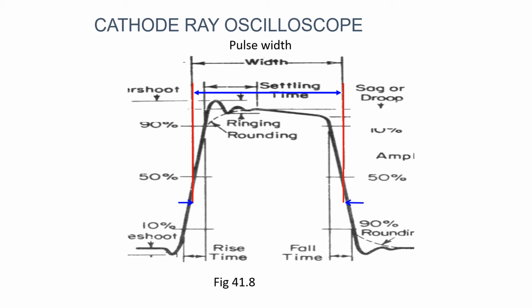So here the procedure, as I already told you, for measuring pulse parameters is, when we are measuring pulses, it is generally desirable to use the pulse source as an external trigger. The essential parameters of a pulse are the amplitude, the rise time, the fall time, the pulse width, duty cycle, delay time, and the pulse repetition rate. So the input waveform has steep leading and lagging edges, while the output waveform has measurable rise and measurable fall time. If the upper wave is the input to a circuit and lower is an output, a delay time might be measured.